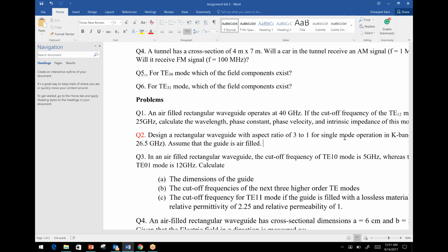So you can be at the edge here, but at the lower end, when you're saying that it has to operate from 18 gigahertz, you have to be careful. You have to do a guard band. So you have to go behind that frequency and say, hey, I want the loss to be low. Again, this is a slightly open-ended question. There's no single uniquely correct answer here.